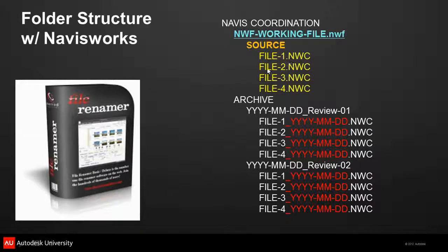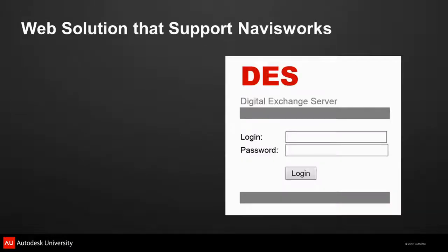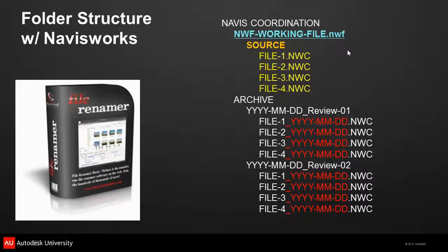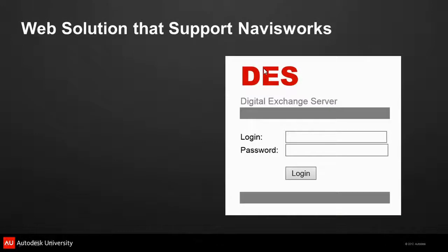How many of you are doing plumbing or using Navisworks Manage with it? Okay, and y'all are doing the projects where you have one source batch of file names and you're not renaming them? Okay, yeah. So that's kind of the standard way you want to do it. And so we use File Renamer to strip them off, and so the clashes will auto-detect. So with File Renamer, we basically get everyone's files, and then we use Renamer to strip off the back and then drop them in the Navisworks folder.